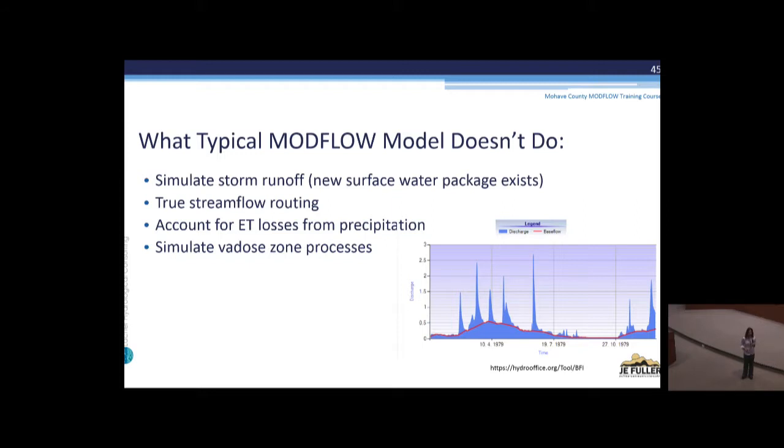And it's going to instantaneously put that water at the water table and add it to the water level of the groundwater system there, across your time step. So it doesn't have this lag in storage. It's basically like the steady state condition is already, the equilibrium has already been set up. So if you want to simulate a new recharge system, it's important to have that vadose zone built into the model in a different way. You probably need a different model just for that system and that very small scale issue.